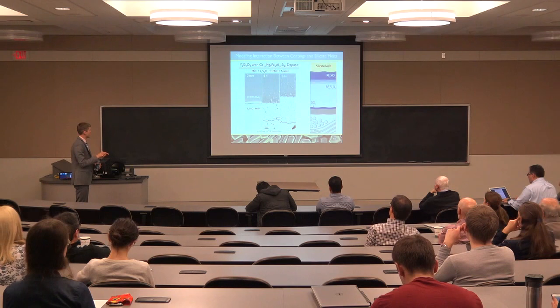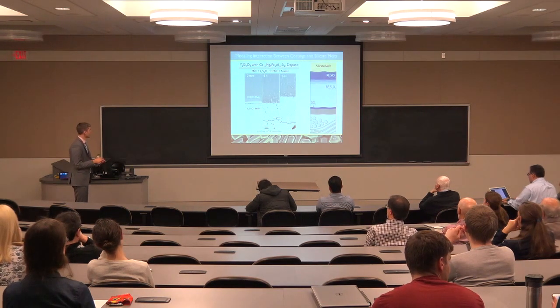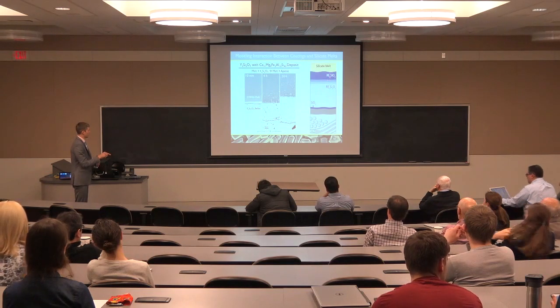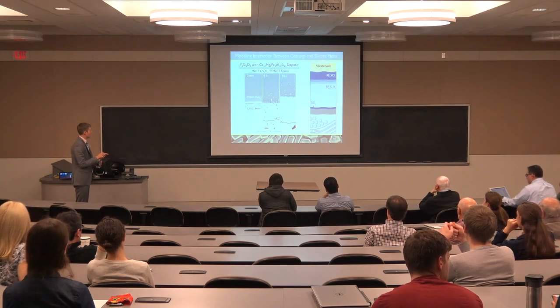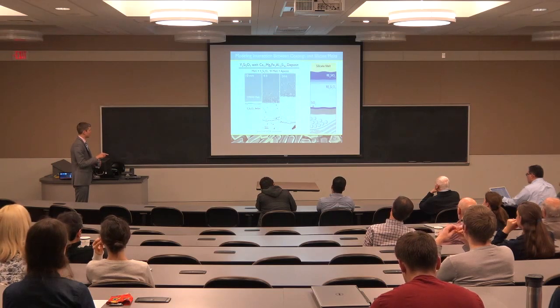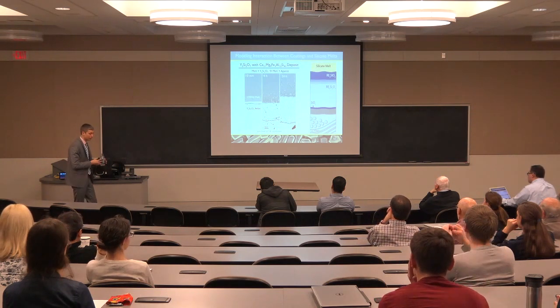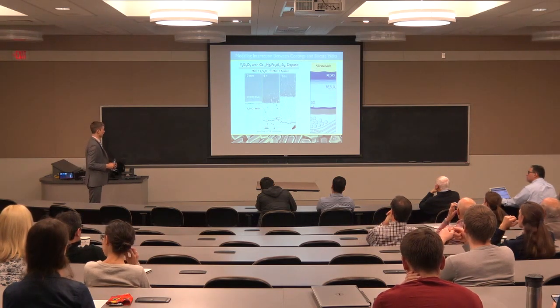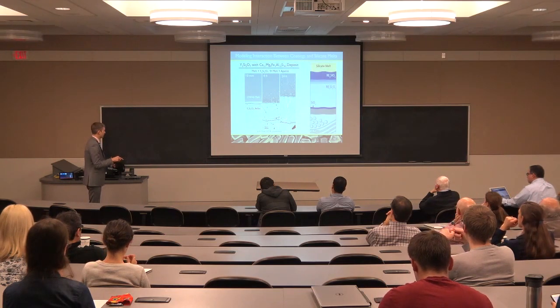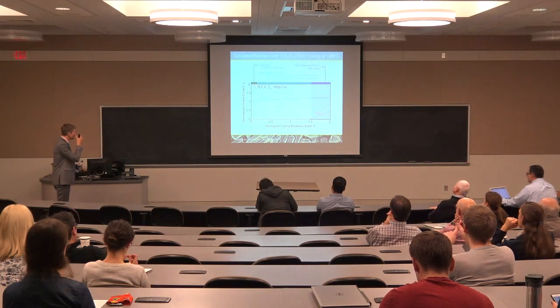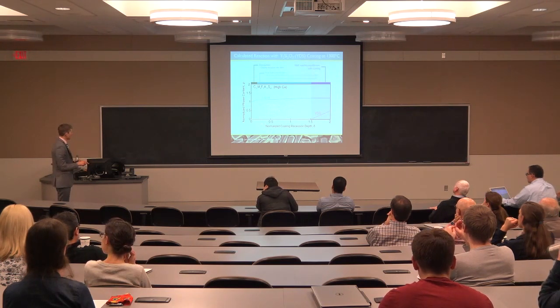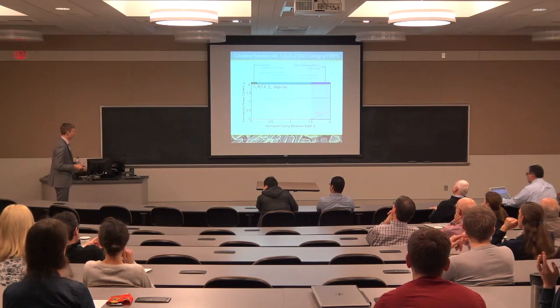So I'll start with an example from this environmental barrier coating system. I'll remind you that here we're dealing with rare earth silicate coatings. What generally happens is when we have this deposit on the surface, it progressively converts the coating to apatite. It has the wrong CTE, which leads to cracking and eventual failure of the coating. So our goal is to minimize the depth of this conversion process for apatite. We can study this if we take a certain amount of deposit and put it on top of a notional coating, and then ask what is the phase equilibrium as the reaction proceeds. Is there still a driving force to form more apatite?